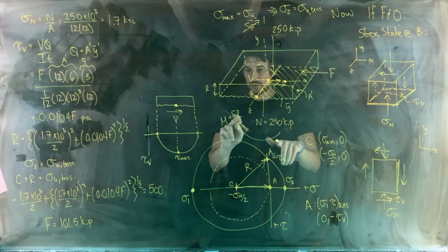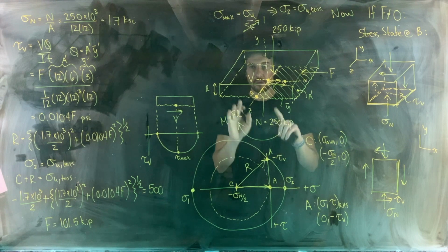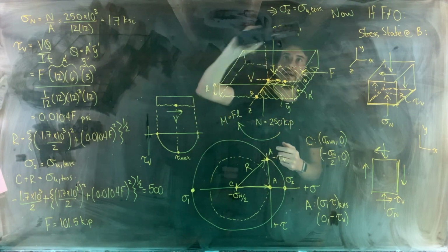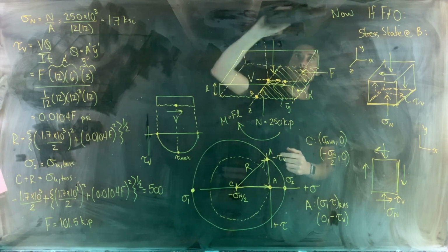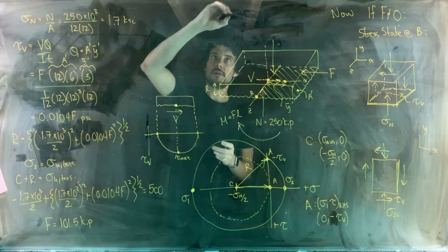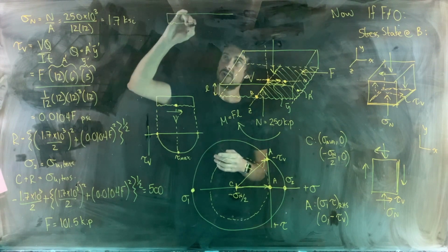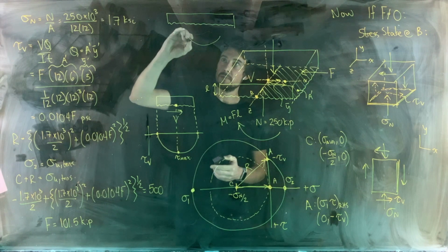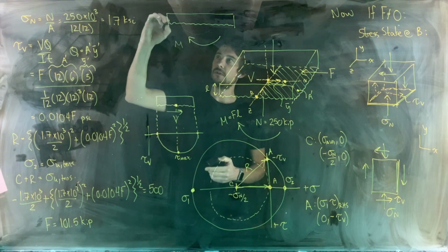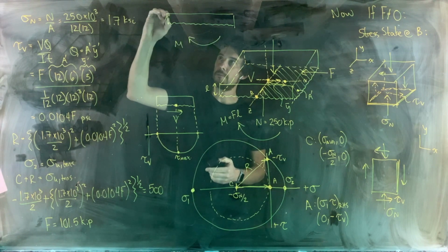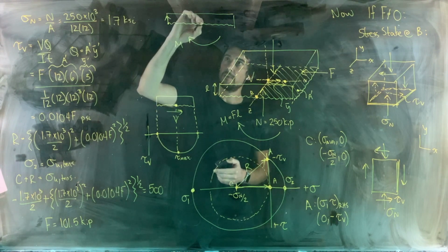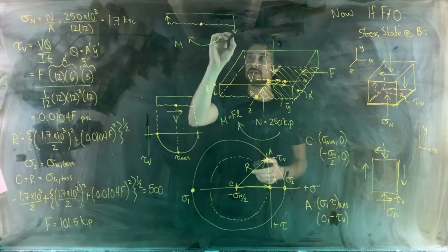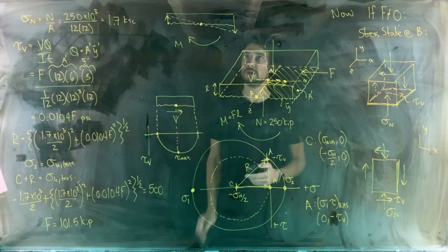That is M equals F times L. And what is that internal moment going to do? Well, if we look at the cross-section in just 2 dimensions here, we've got an internal moment that's acting around like this. So it's going to take this side of the cross-section and push it in compression. Moment's acting about the centroidal axis. It's going to take this side, pull it out in tension, and there'll be the linear transition between those two.